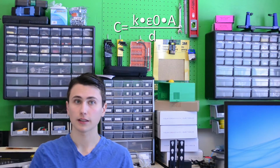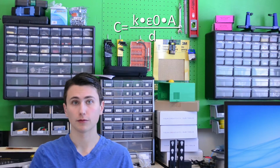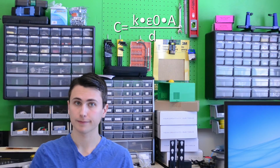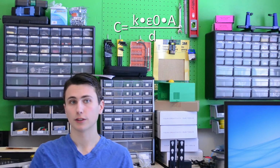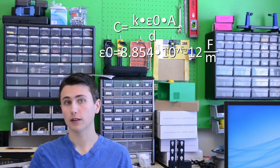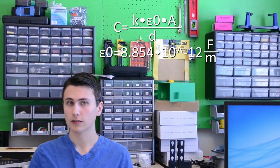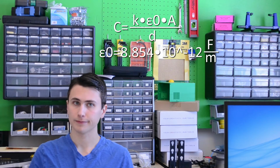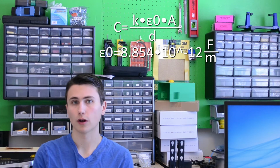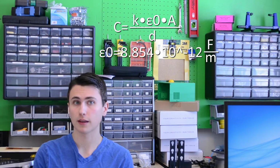Capacitance is equal to the dielectric constant times the permittivity of free space times the plate area divided by the distance separating the plates. The permittivity of free space is 8.854 times 10 to the negative 12 farads per meter. So let's think about this for a moment. We can buy surface mount 0805 capacitors with a value of 100 microfarads. Micro is an SI prefix that means times 10 to the negative 6.